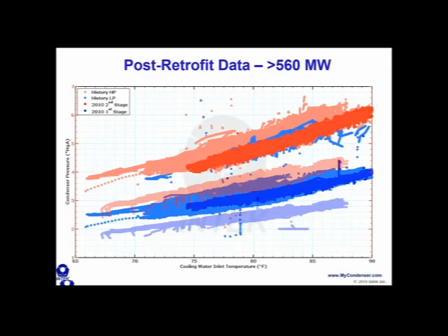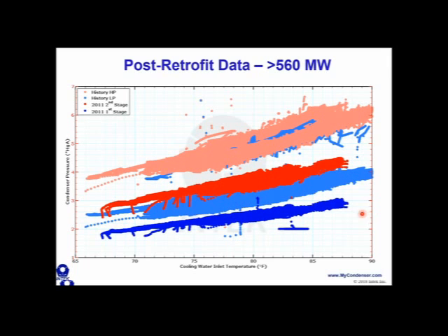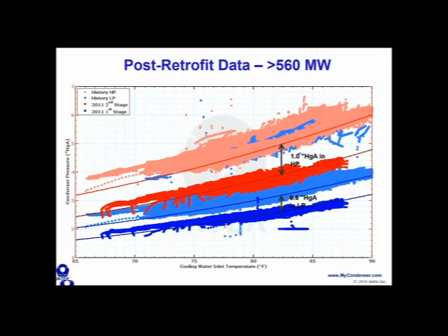And then we installed the condenser retrofit. Look at this. So we installed a much more effective air cooler section, and look at the pressure reduction. HP shell dropped an inch of back pressure in the HP, 6/10 in the LP. Okay. Keep in mind this design wasn't good to begin with. That's where the opportunity came from. But an inch in the HP, 6/10 in the LP. A really nice benefit here.